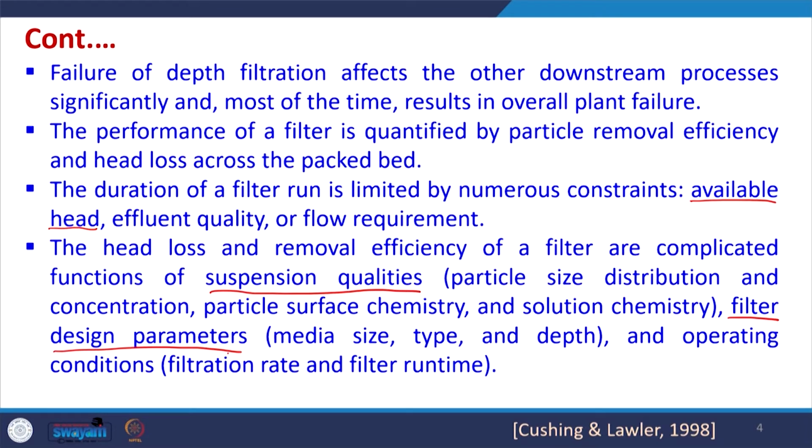In the suspension qualities, the particle size distribution is important, the concentration, and the particle surface chemistry, whether it is getting attached. If the particle surface chemistry is such that it is getting attached by a chemical bond to the filter media, then the backwashing will become difficult. What is the solution chemistry, what is the pH, all those parameters affect the removal efficiency in a filter. So, that is there.